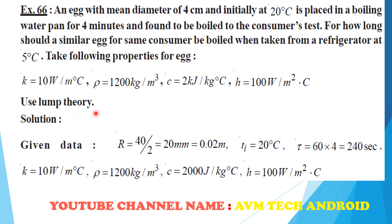So if you do not calculate the Biot number, no problem. Otherwise we have to calculate the Biot number, and if it is less than or equal to 0.1, then and only then we go for unsteady state heat transfer. The radius is available in millimeter, convert into meter. Initial temperature is 20 for the first case, time is 4 minutes, so 240 seconds. Thermal conductivity is given, density is given, specific heat is given, and h is given.